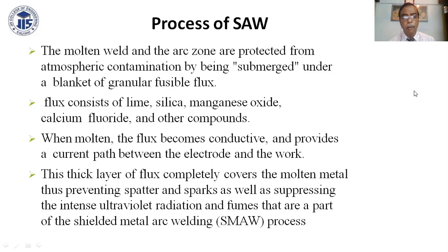This thick layer of flux completely covers the molten metal, thus preventing spatter and sparks, as well as suppressing the intense ultraviolet radiation and fumes that are a part of the shielded metal arc welding process.